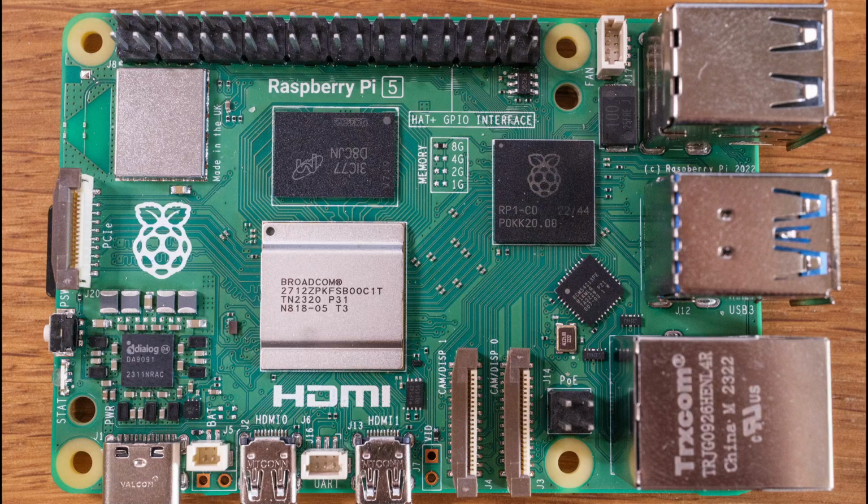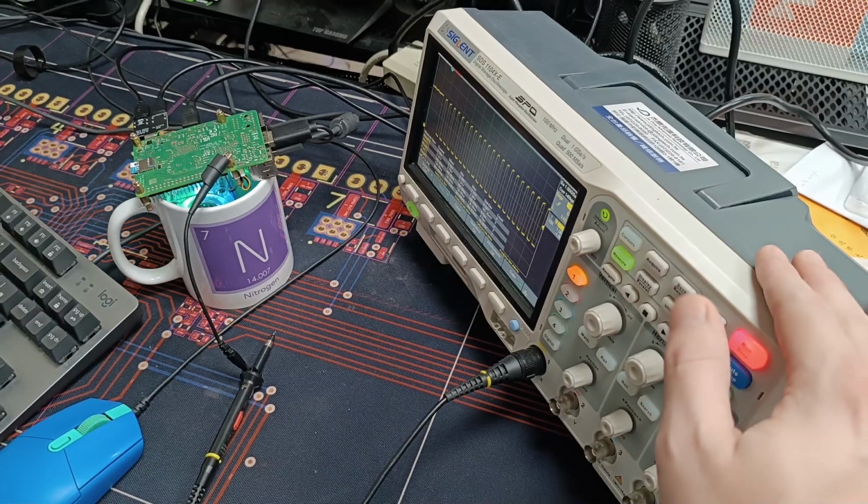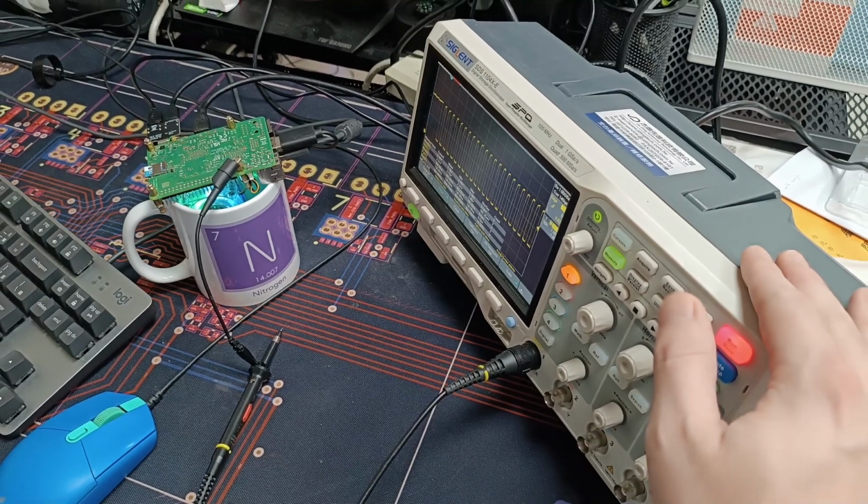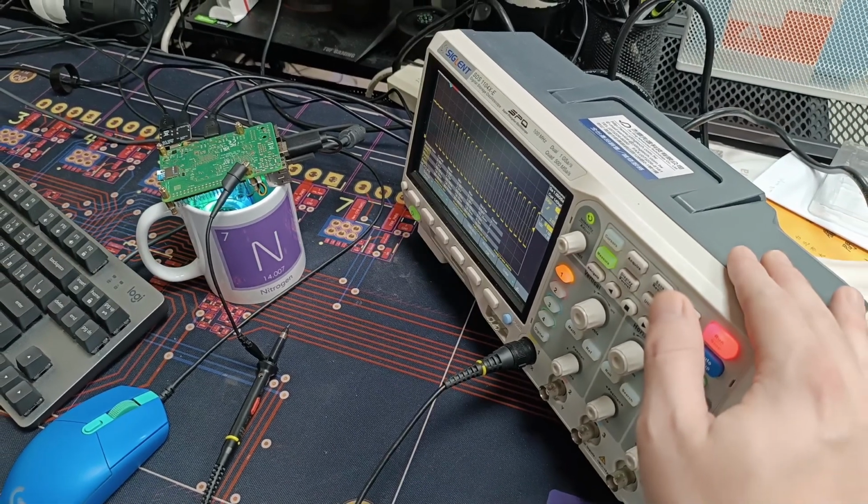However, sometimes the I2C pins are also exposed on the PCB. So I called upon Elmor's expertise to search for the I2C pins. So how do we identify these pins? Well, trial and error and 2 tools, our telemetry script and an oscilloscope. Essentially, while the Raspberry Pi is running, we check each exposed pin for either a clock or a data signal.